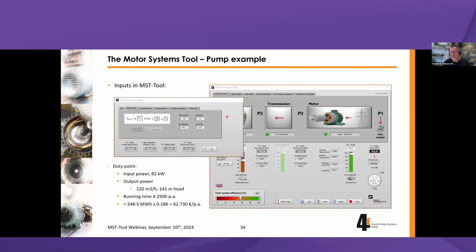So, in conclusion, from very little input, you can calculate and understand an entire pump system: what your flow is, what the efficiency of the pump is, and so forth. You can even use it if you have access to your pump curve. It's actually possible because now you know the shaft power, so you can go into the pump curve and have a good estimation of flow and head of the pump. If you don't have access to that, it would at least give you an idea of what the flow would be if you have the pump curve. So, quite efficient, I think, in my mind, at least.